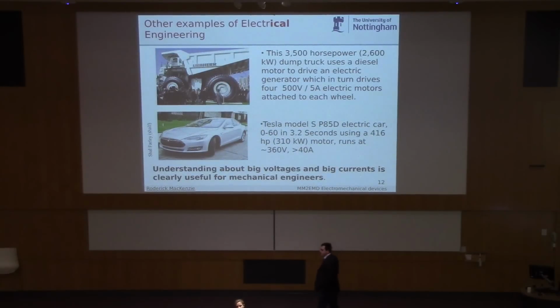And it's electrical because, of course, we all know the torque of electrical motors is very, very high at 0 RPM. So you get maximum torque from an electrical motor at 0 RPM. And that's not the case with a diesel motor. Obviously you can imagine this thing being full of rocks and on a slope, and you need all your torque to start off. So what they do is they use a diesel motor to run a generator, so you always keep your diesel motor running at the optimum condition. Then you use that to power the electrical motors that are attached to the wheels, which means this thing has got massive torque at 0 RPM. And you'll figure that out if you look at the induction motor torque speed curve.